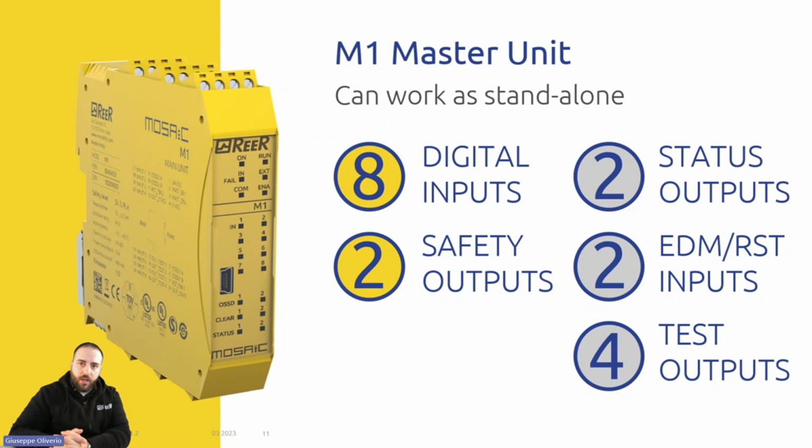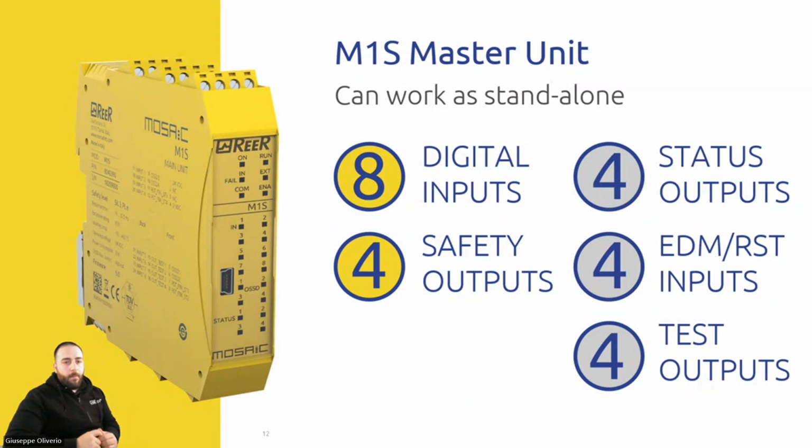So in the case of every switch, emergency stop or interlock switch with electromechanical contacts, you can test them by using the controller, without doing any other wiring or any other change, just from the software.